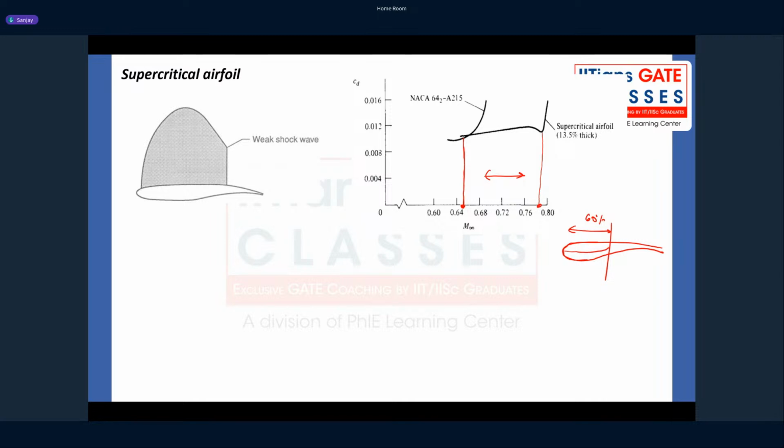Any aerofoil placed in a negative camber will lose lift. So if I lose the lift here, I need to gain that lift. To compensate, in the remaining 30%, I will provide extremely high positive camber. Because of that positive camber, the lift lost here is recovered.